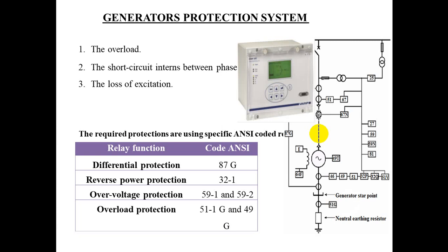The modern practice is for the regulator to unload the set via the secondary governor until normal vacuum conditions are restored. If the vacuum conditions don't improve below 20 inches, the stop valves are closed and the main circuit breaker is tripped.